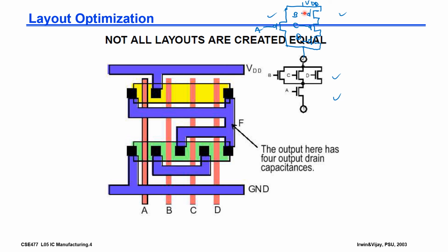And then since B, C, D are all contact using diffusion layer here, we do not need to put any metal contact. And for the VDD part, this is a VDD, should be contacted to the B side and also to the A side, the source side here. So you have a A here and B here. You should put a metal in between these two, so you have it all connected, right? I hope this one clear.